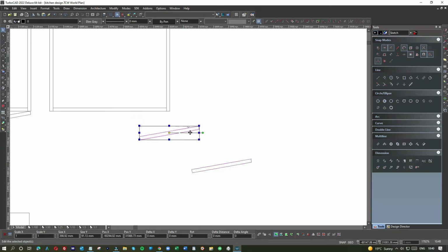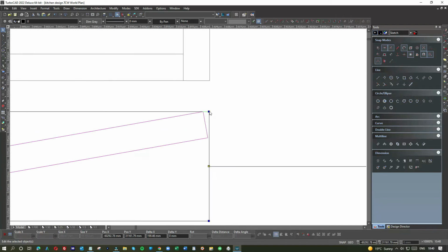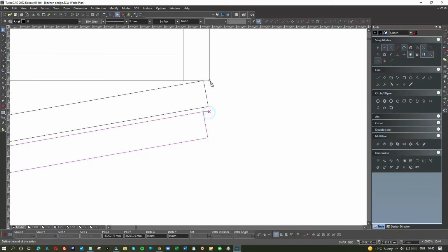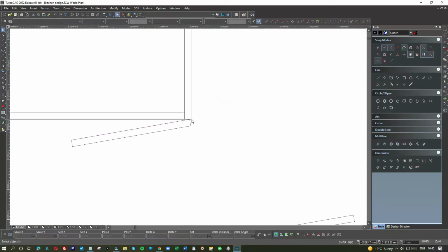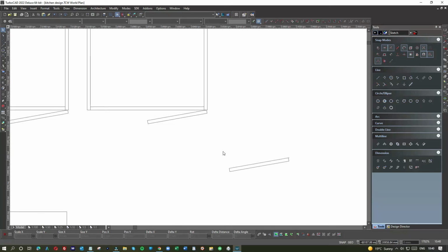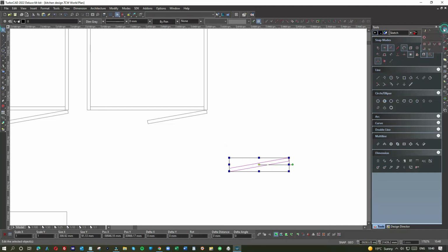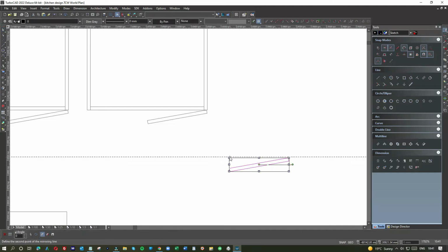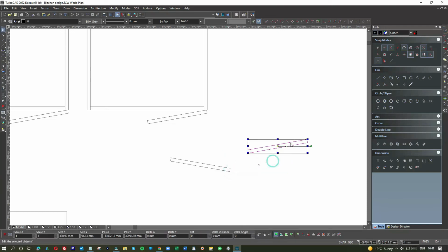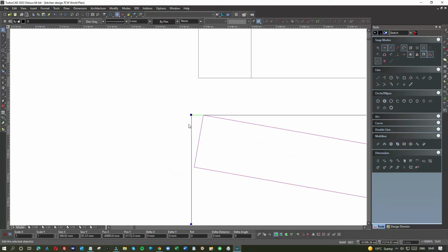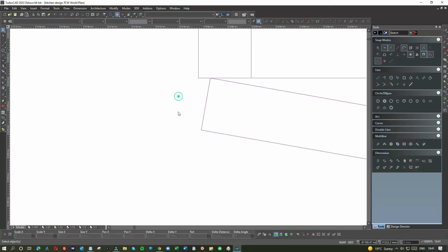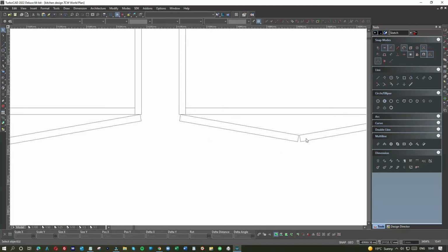Right. So let's show the door. D. And then it's very easy. I just pop it onto the corner. I know it's 5 mil in, and I know it's 5 from the center. Now, as you can see, I need to do the other side. The simplest way of doing that is a mirror copy, and we don't really need this one. So now we do the mirror copy, and again I use the D to change the yellow circle. There you go, and that's a proper join.